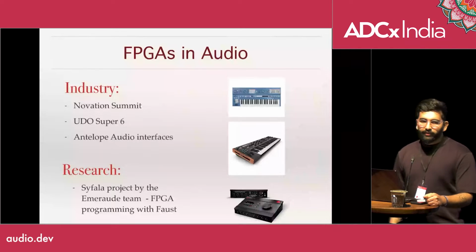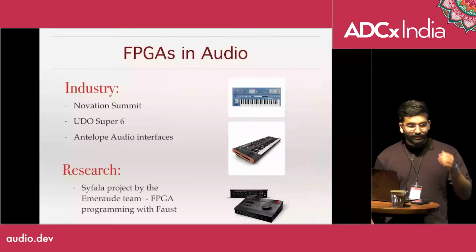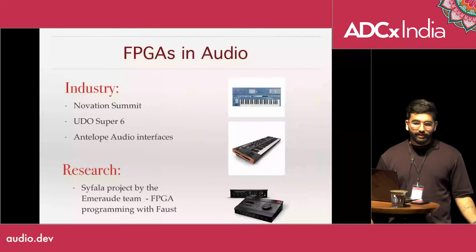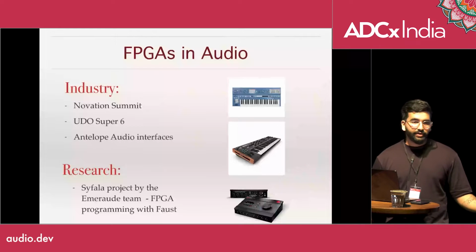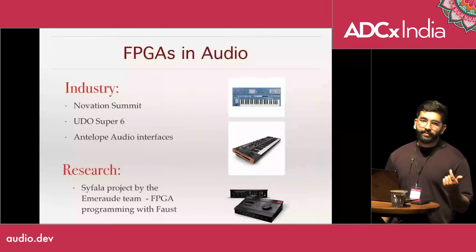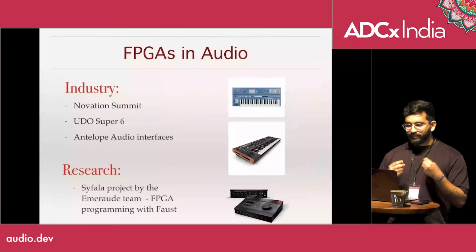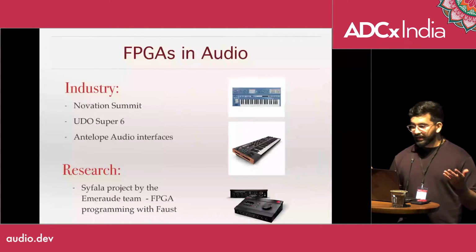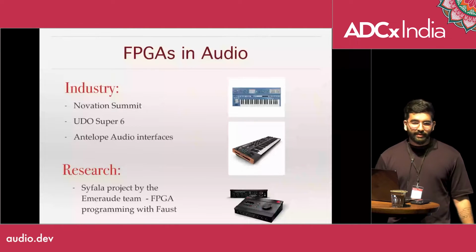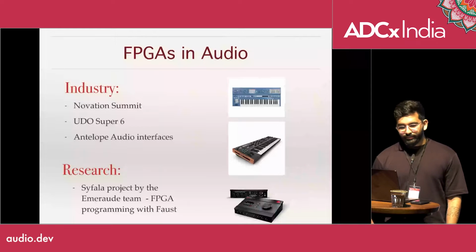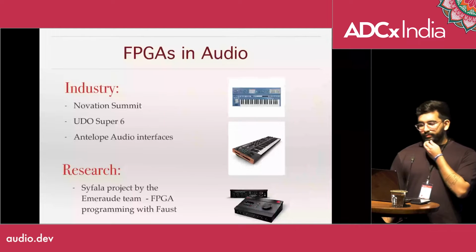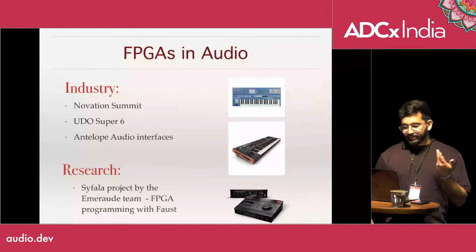Some examples of FPGAs in the audio industry and in research: the first, a synthesizer example, is the Novation Summit. The oscillators are virtual analog oscillators, run at extremely high sample rates to achieve the sound. If you hear it, you'll know it sounds really good. Even the UDO Super 6, similar thing, the oscillators are run on FPGAs. So they leverage the super high sampling rates.